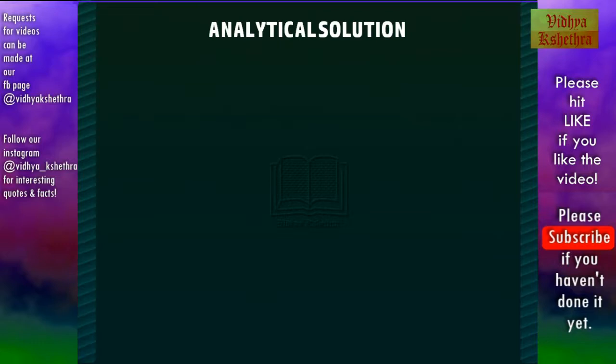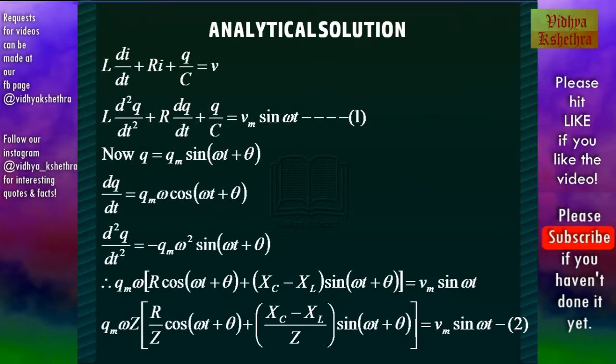Now, this is the second method of arriving at the solution. That is the analytical method. In this, we write i is equal to dq/dt. Therefore, the equation L di/dt plus Ri plus q/C is equal to V becomes L d square q by dt square plus R dq/dt plus q/C is equal to Vm sin omega t. Let it be 1.